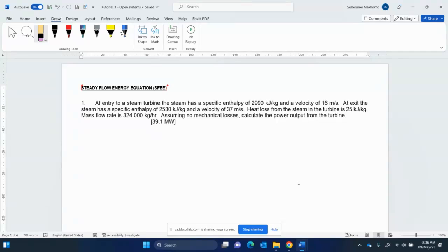Similarly, with the compressor, if you do your calculations and you find that your compressor input power is positive, that is a mistake. Your compressor is always negative. So negative does not necessarily mean that there is such a thing as negative power. It actually shows the direction of flow. So that's where we are.